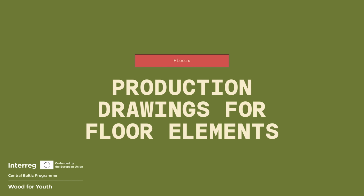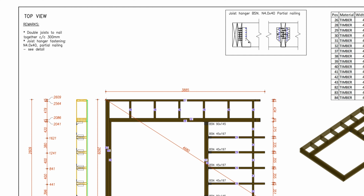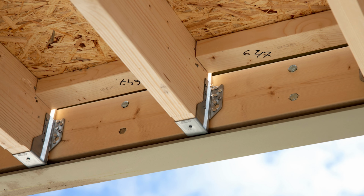Let's start from the first drawing, assembling the wooden frame. In the upper left corner, you see from what side the view of the drawing is. For instance, in this case, the view is from above, as the next layer is constructed on top of the element. Also, you see additional remarks that are related to fastening the beams and fixers. There is also an additional sketch showcasing how to fix the beam shoe, as the fixing system can be different depending on the project. A beam shoe helps to connect a beam with another structural component.